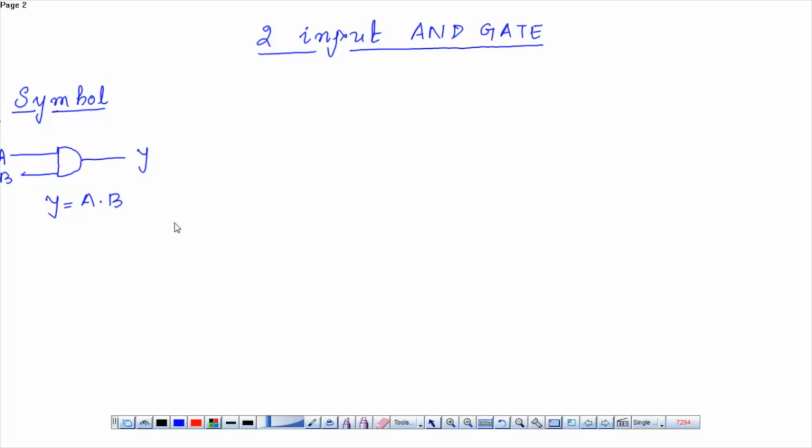We can directly use the NMOS and PMOS and design a schematic diagram, or the other way to represent this Y is (A dot B bar) whole bar, which is NAND. You can see this A dot B bar is NAND plus NOT to invert this whole bar.